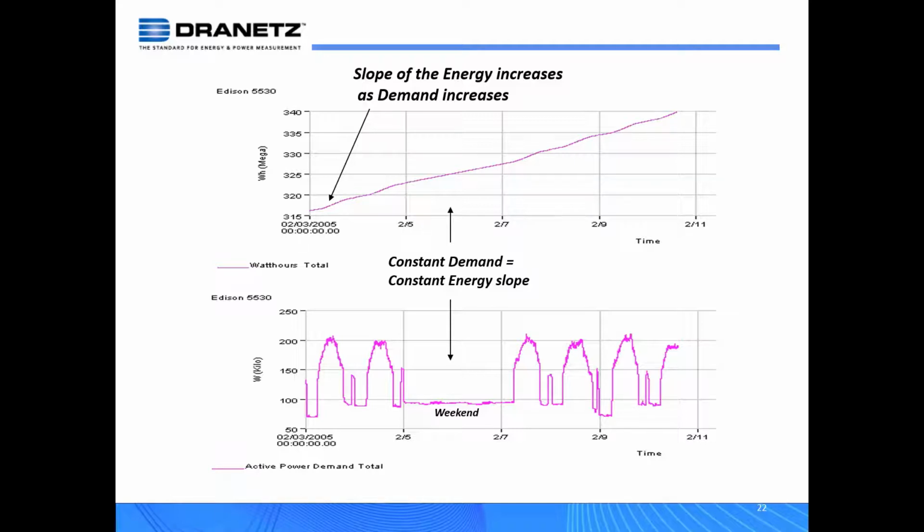You can look at the power signature and the demand. Let's say all of a sudden I'm monitoring a building, a whole bunch of boxes moved in and the demand goes way up. Okay, you look at the PQ wave shapes, it looks like electronic loads. So it looks like computer servers were put there. So that's kind of a hypothetical, but also a type of real application, and kind of looking at this application and looking at this information.